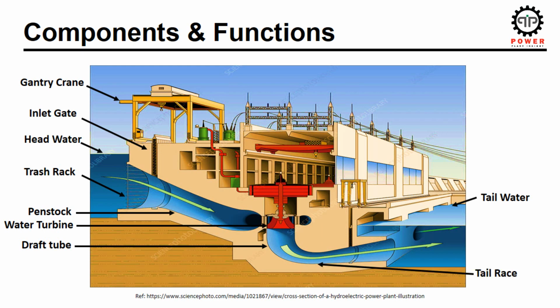Tail race. Tail race is the water channel that takes the water out of the turbine. It is usually located at the outlet or exit of the turbine and converts the kinetic energy of the water at the outlet of the turbine to pressure head. Similarly, an outlet gate is provided at the outlet of the turbine. It can also be used to isolate the turbine from the water reservoir and from the tailwater.